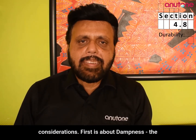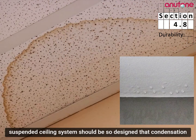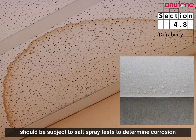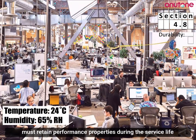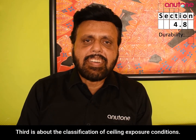First is about dampness. The suspended ceiling system should be so designed that condensation does not occur. In case momentary dampness does occur, the ceiling must not show any damage on drying. Metal framing should be subject to a salt spray test to determine corrosion resistance. Second is about service life requirements. A grid ceiling must retain performance properties during the service life when exposed to normal occupancy conditions, subject to receiving periodic maintenance with no ill treatment.